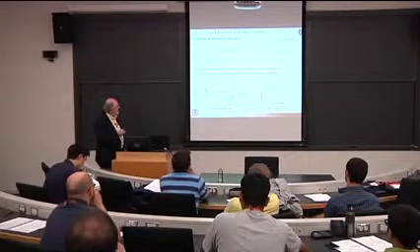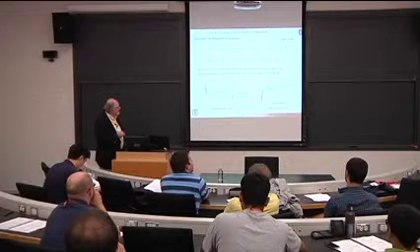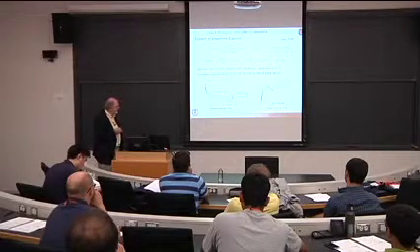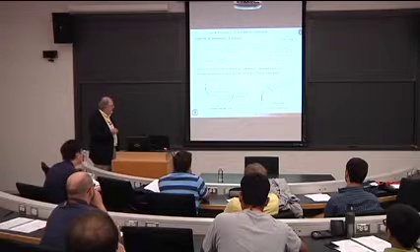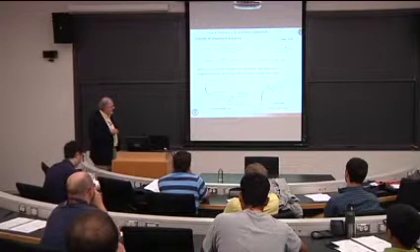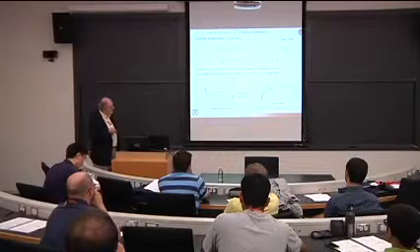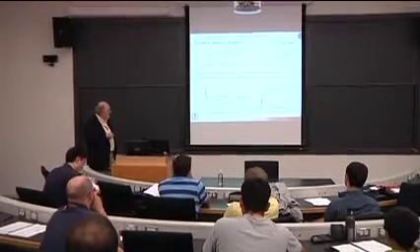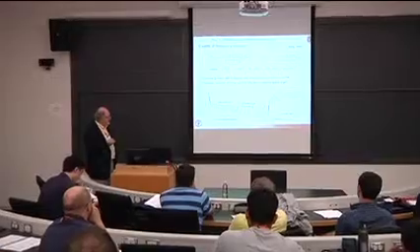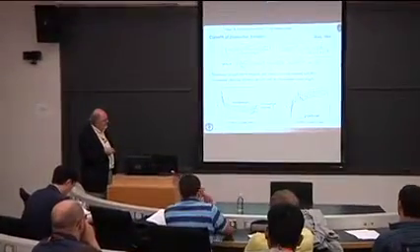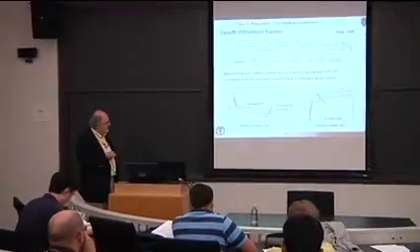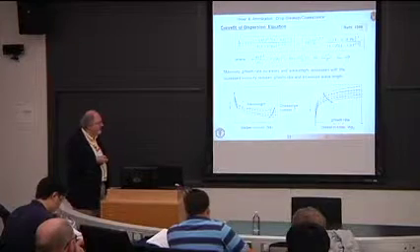And if you look at these curve fits and compare them with the theory, you see we do a very good job here. Here I'm plotting the non-dimensional wavelength against the Weber number. Symbols are the results of this curve fit. The lines are from the complete theory. And you can see that, as we said before, if we increase the Weber number, the wavelength decreases. This is a log plot here, so it's a significant decrease in wavelength.